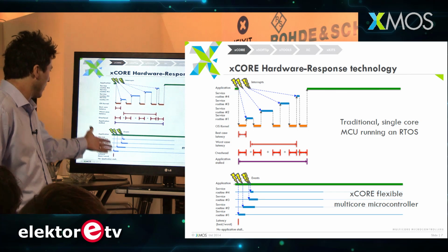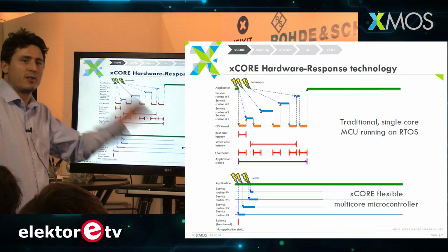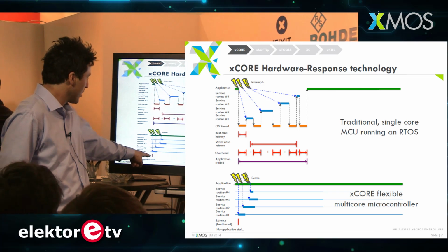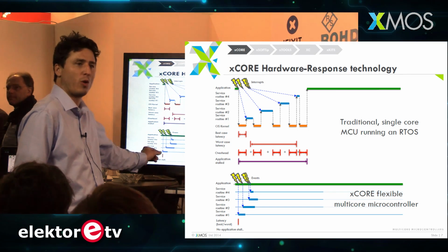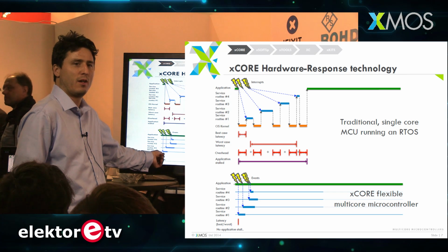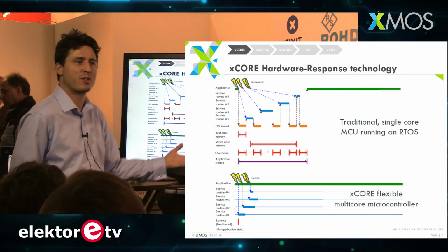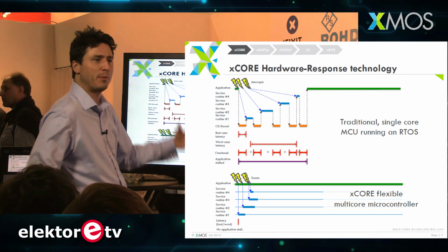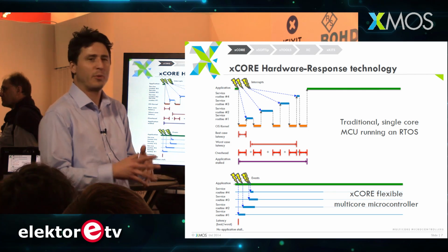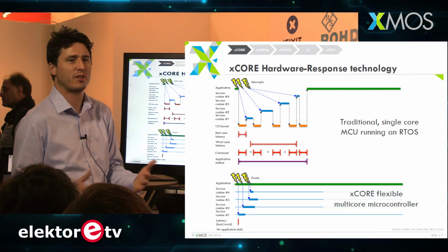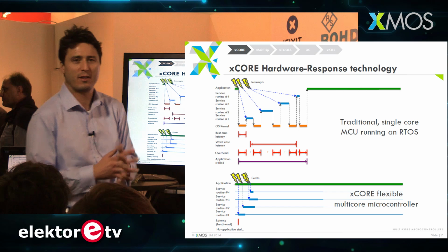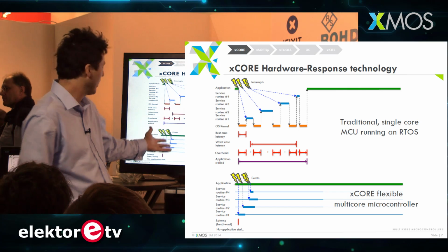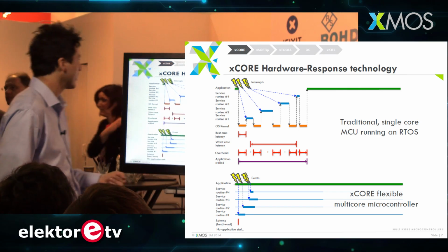In contrast to that, on the XMOS architecture, we react immediately to an event because the cores do not interfere with each other. And you see that the response time to an event is very low and always constant. And that means we are deterministic enough to do hardware and software. You see up here in the interrupt-driven system, your latency varies depending on how many interrupts occur. And that brings non-determinism to the application, which is bad for real-time performance, right? So here you see in one glance the advantage of the event-driven execution scheme of XMOS.